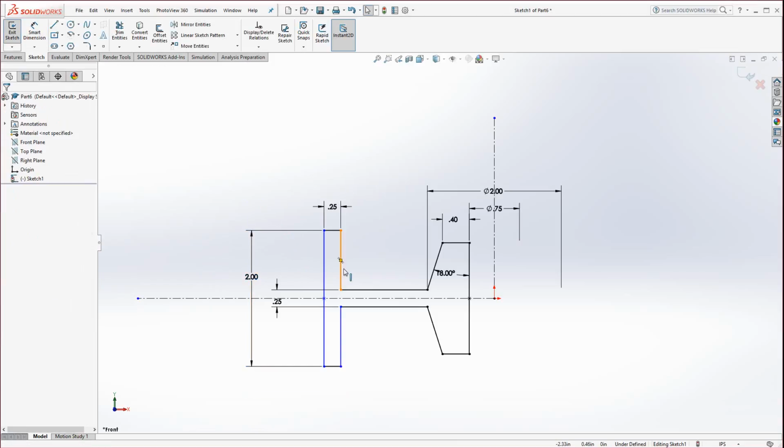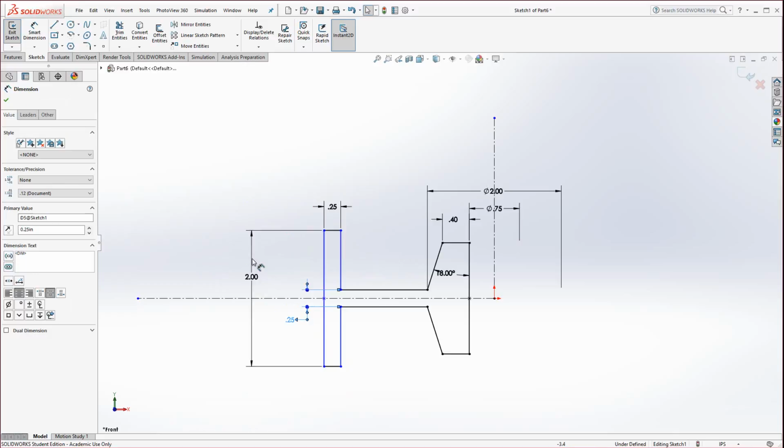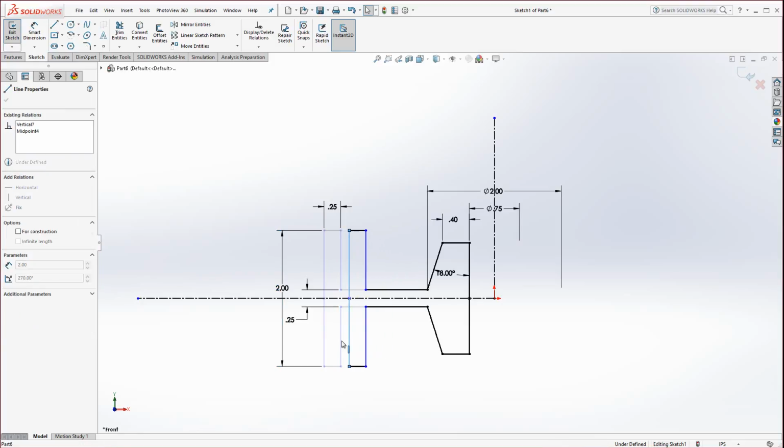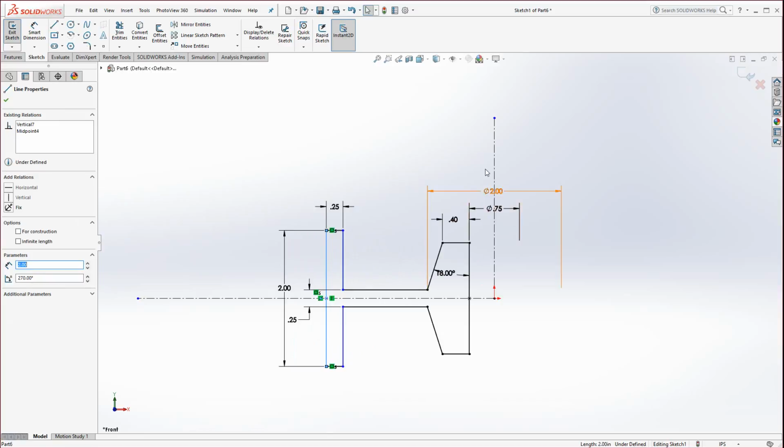And hit escape. Now you'll notice this geometry is blue. A number of students that I've taught over the years seem to not see this last dimension that's in the actual manual. Again, if you're not sure what is left over and you see it's blue, it means it's underdefined. As I always try and teach, make sure it's fully defined before you go into production. So you could just grab this after you hit escape, just drag it. And you can see it's missing the 5-inch dimension, which is the overall diameter of the wheel.